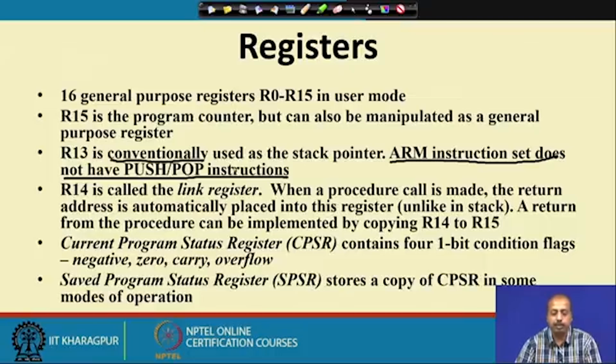So, you do not have stacks available in ARM. It seems very surprising, because in the program that I am writing there may be subprograms, and if the stack is not there, how am I going to save the return addresses of the subroutines, and how am I going to pass parameters? There are many concerns. What the ARM designers possibly thought is that it depends on the program. Many programs may not need to call a subroutine.